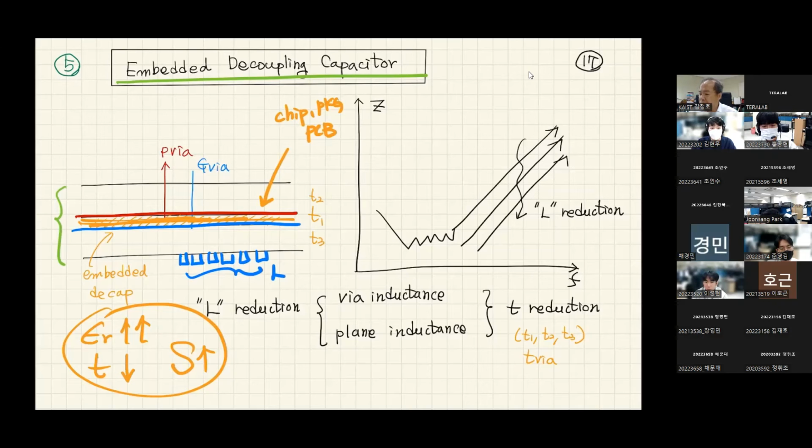And if we put the via, in this case, we can put many vias, 1,000 vias, because this is two-dimensional. So the number of vias will increase significantly. By having that kind of structure, we can reduce the inductance at higher frequencies. The initial design has a certain inductance.